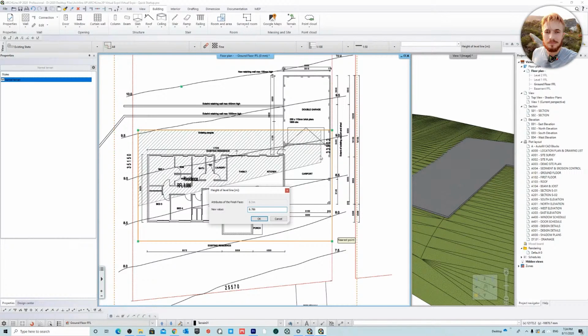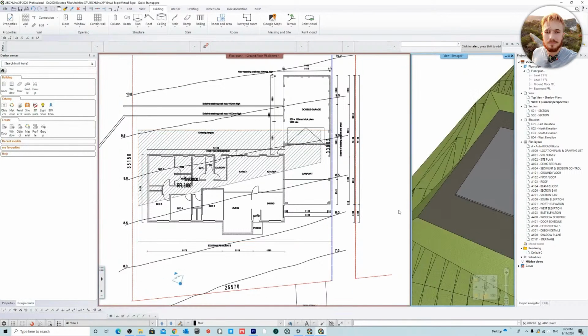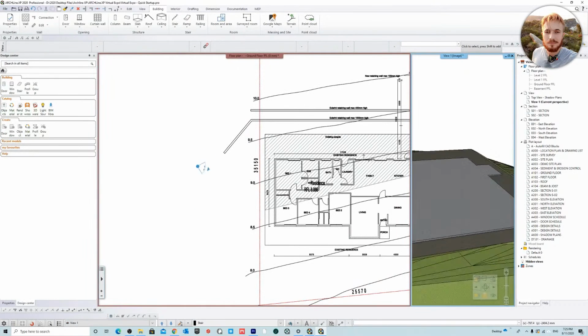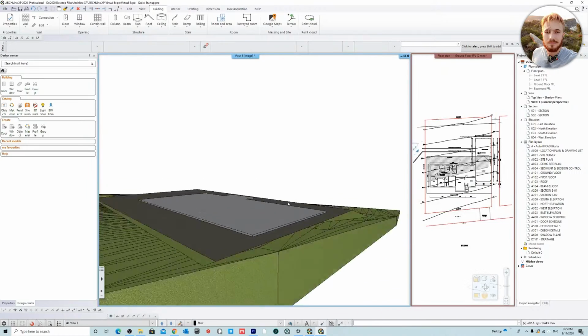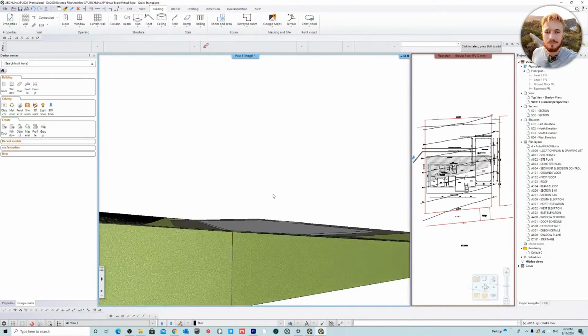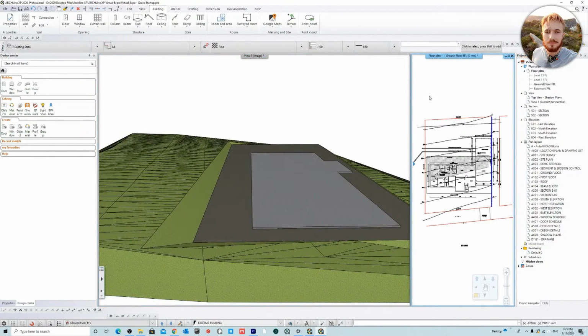So that means that this flat part is going to sit beneath the slab. Okay, so if I just go okay, and I'm going to select an inclination angle, and that's just the terrain surrounding it. So what we've got to do now is maybe just put in 60 degrees and see how that looks. Okay, so you can see now we have a building footprint, a building pad, and we'll just go back here. Now you can always make this a little bit smoother.